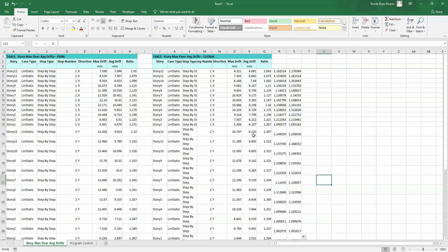We have followed all the steps to characterize the structure, define its behavior, determine its behavior coefficient, define its structural system, perceive whether the structure has torsional susceptibilities, and verify that the distinction between the primary and secondary structure is correctly defined. We now end this first section and move into a Q&A phase to dialogue with the trainees.